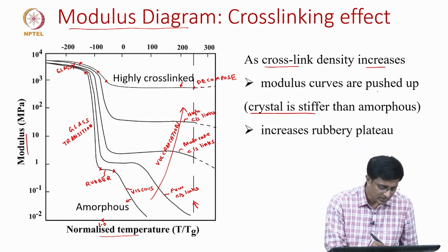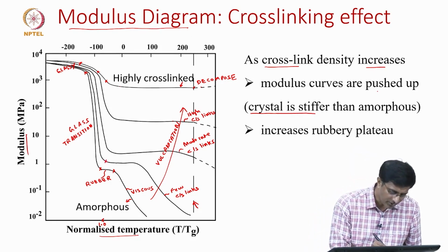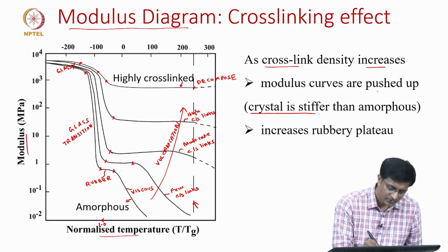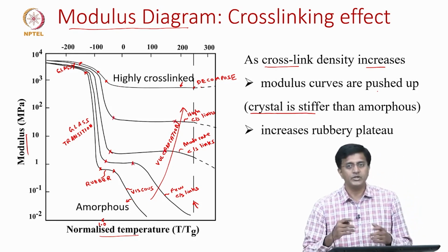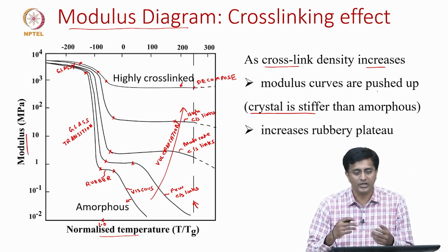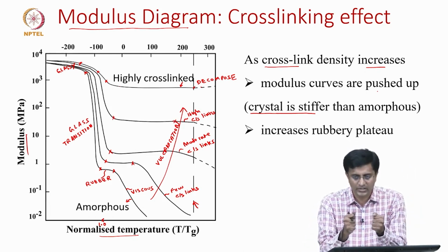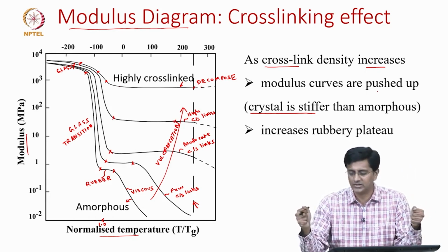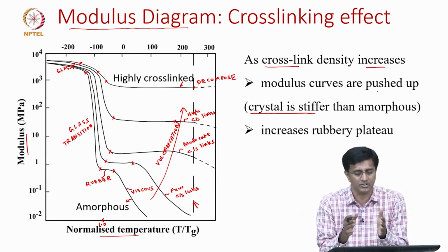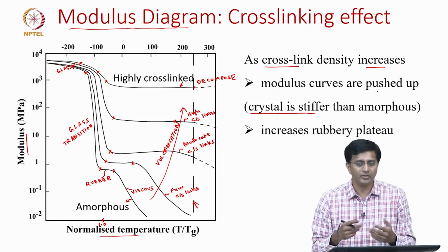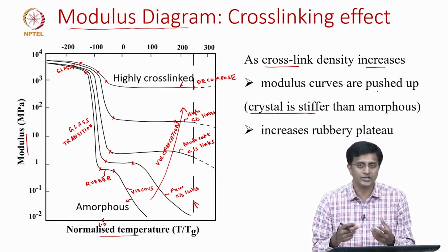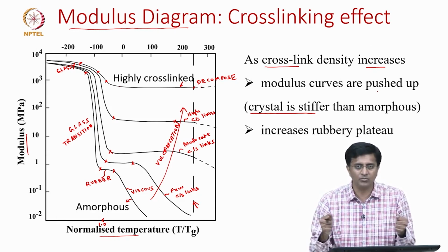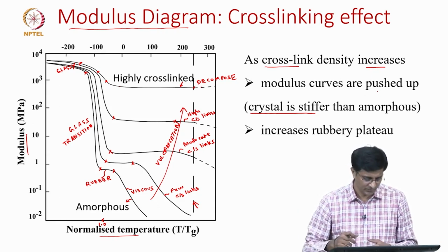And we also see that the amount of rubbery behavior increases. So, which means if we want more and more rubbery behavior, what is rubbery behavior? Where it stretches for large strains and when unloaded it comes back to the original shape. So, if we add more concentrations of sulfur, that is when we can see more of this rubbery state.